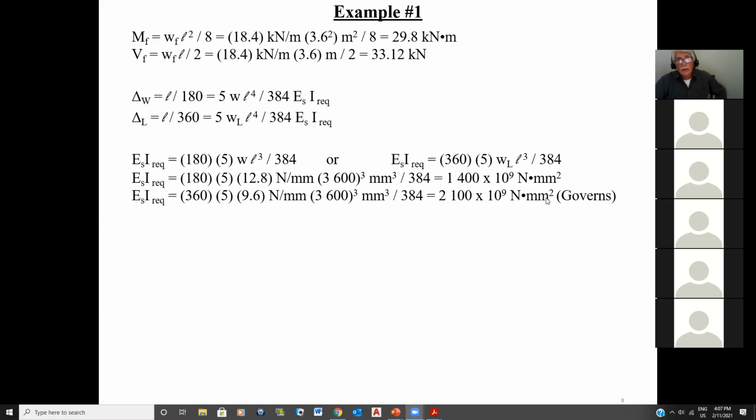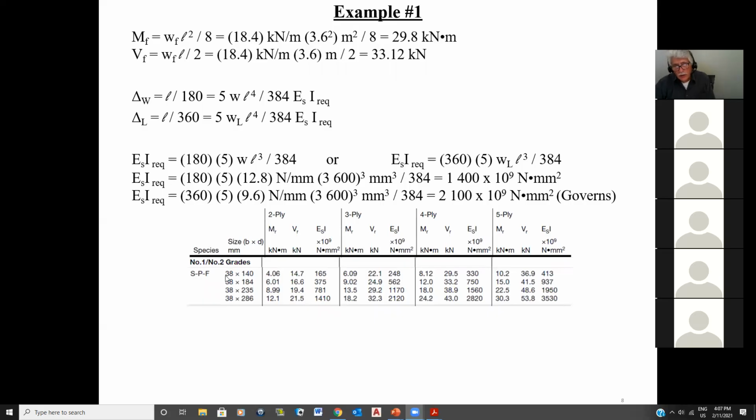Well, I've got everything now. I've got what I need for strength. I got what I need for serviceability. So since KD is 1, KS is 1, KT is 1, KL is 1, everything is 1, yes, I can go straight to the built-up beam table. And of course, here, what I did, I extrapolated that one section that applies to us.